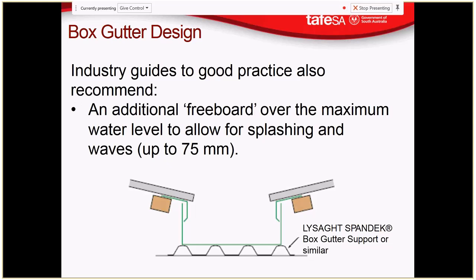Personally, what I prefer is, say, a 2,000 litre tank with a submersible pump in there, and then your downpipes going into there. Then at least you've got some warning. So you go, oh, look, the tank's full of water, my pump has stopped working. At least you've got a chance to look at that before all your water goes to the neighbours. But specifying that sort of thing in a roof, where you had a submersible pump in the roof, and the result of that failing is you flood the building. It's possible, but it's dangerous territory.